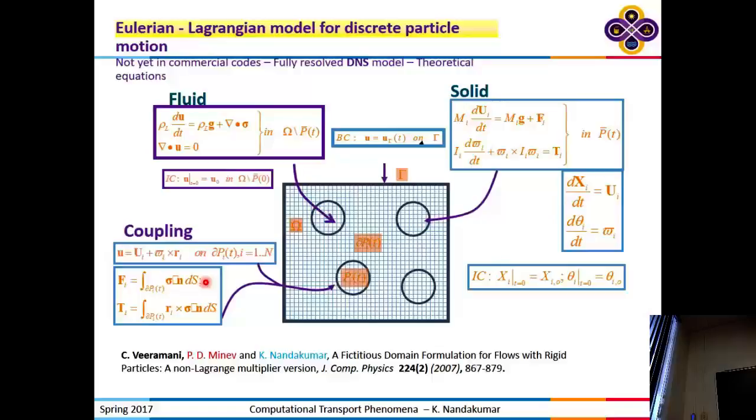So this is an integral of the shear stress over the surface that gives you the net force. And the net force may have any direction. And you can resolve that into three orthogonal directions and call it drag and lift. But here it predicts those things. You can actually compute that. And that goes into determining the forces acting on the particle.